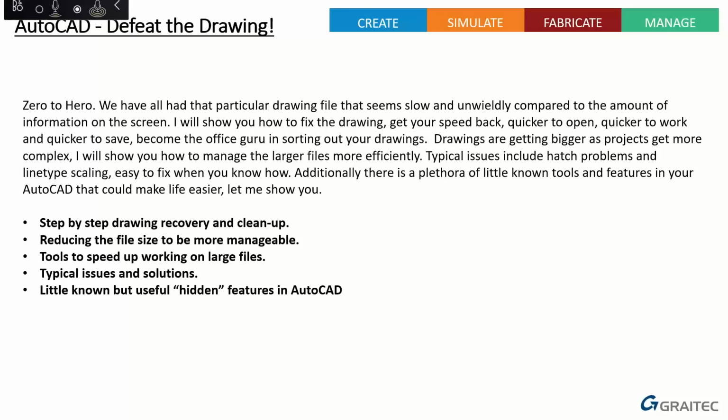Then I'll go through some typical issues and, more importantly, the solutions. Folks had a lot of problems with hatch patterns, trying to get those correct, or line types. That's another good one. Why is the line type not showing up? Or why is this one showing up and not the other line type? That kind of thing. And then some useful little tips and tricks. I've called it hidden features. They're not hidden, nobody just tells you about them. But it can be quite useful. So that's what we're going to be going through.